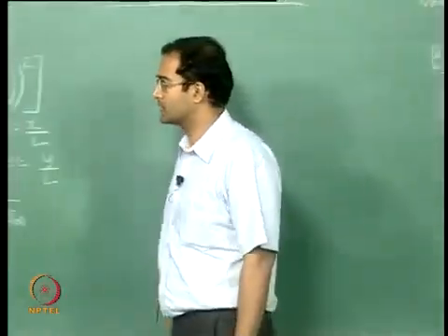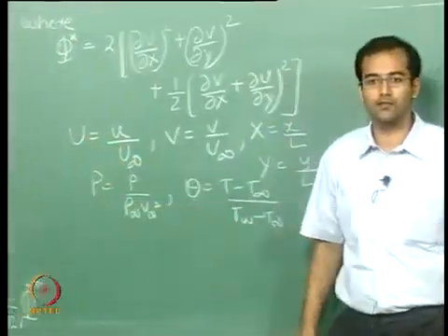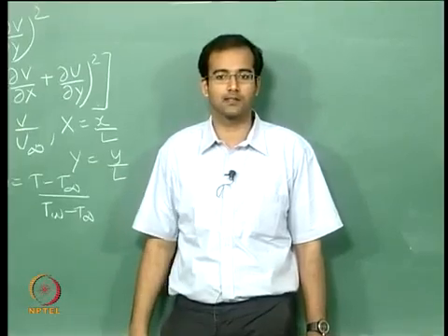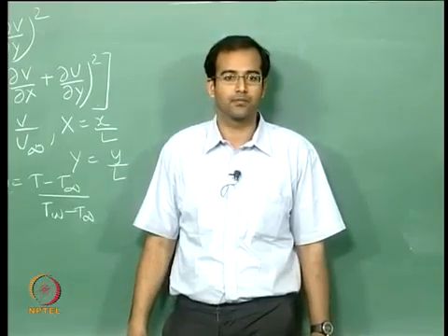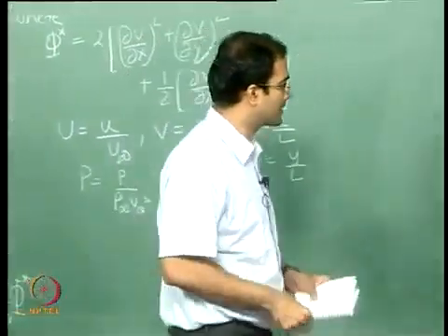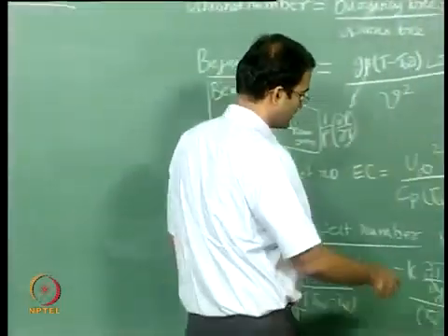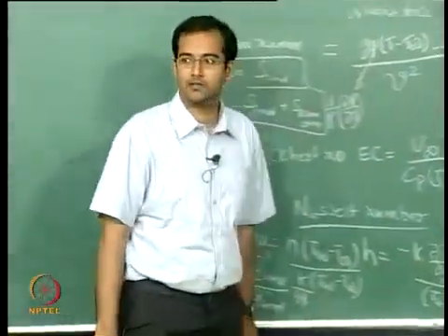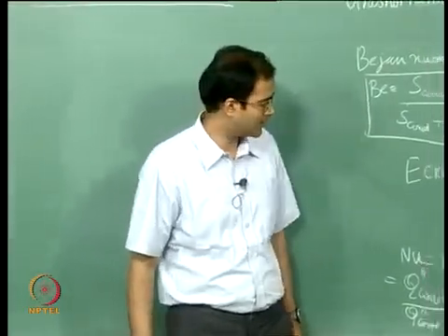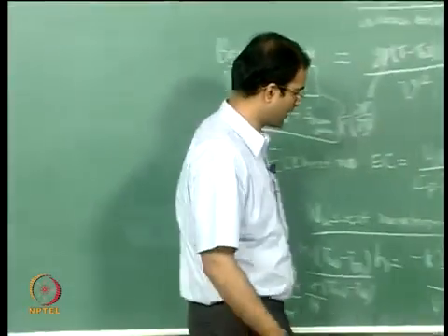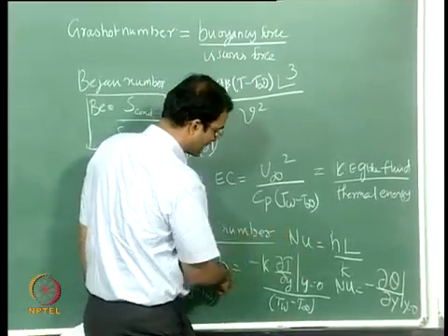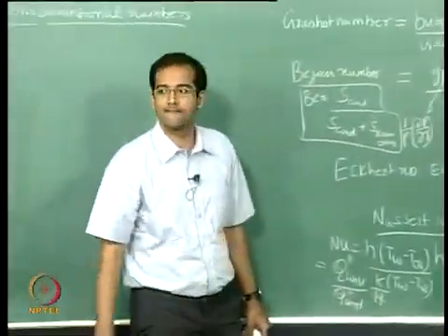The Richardson number is, as I said, if you group your Grashof number by Re square, and you group them together as another non-dimensional number, that is called the Richardson number. K disappeared. This is h L by k, so k should cancel. I think it's straightforward, right? Your k cancels. If you divide h by k, it directly cancels.